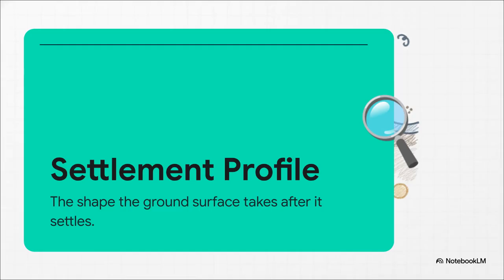Right, so the second phenomenon is the settlement profile. This is the actual physical shape the ground surface takes after it settles under all that weight. Just imagine a curved line showing the exact dip in the earth. Now here is the absolute secret to everything we're going to discuss today. These two things, contact pressure and settlement profile, they are inextricably linked. The shape of one depends entirely on the other. But, and this is a big but, it also depends on two massive variables: whether the foundation itself is flexible or rigid, and whether the soil you're building on is clay or sand.